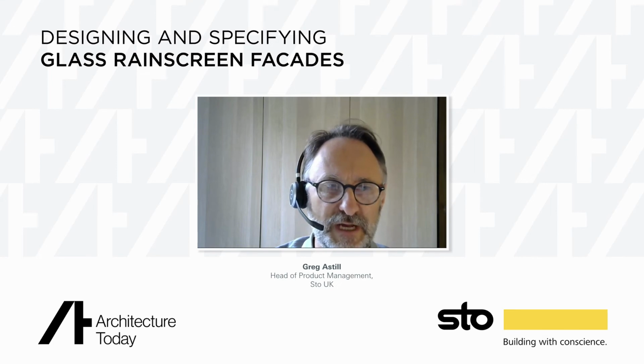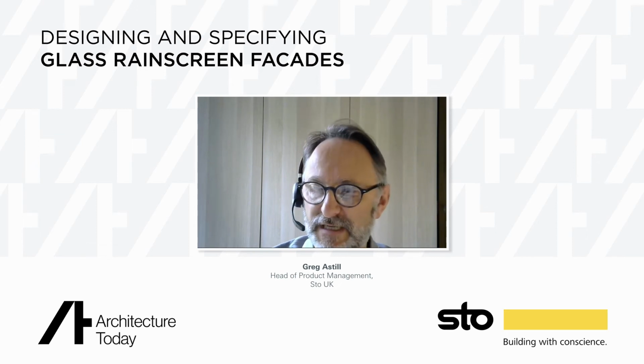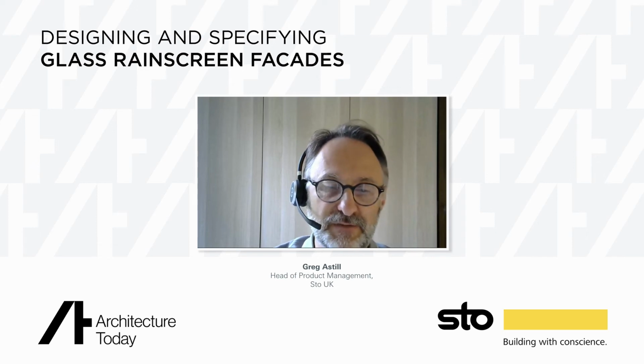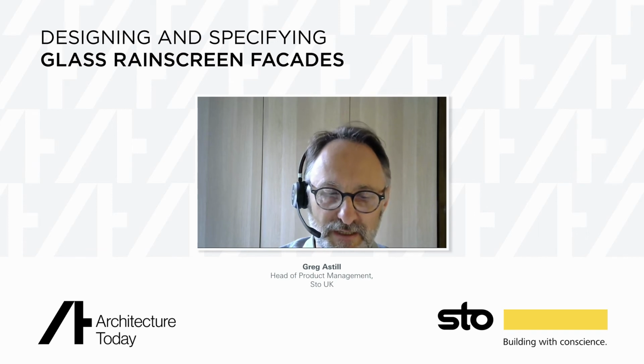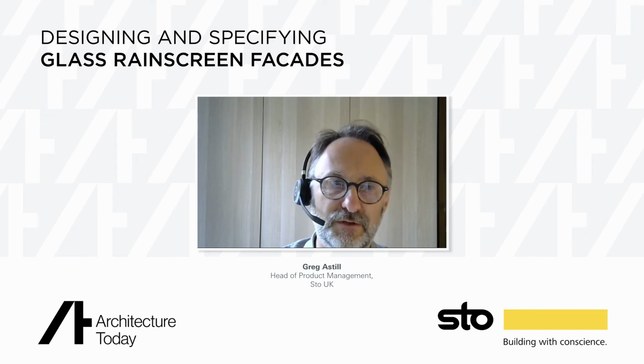So that intumescent material expands, blocks off the cavity, if you like, so the fire cannot get past it. It also stops any smoke going up through the cavity as well. So that's how they perform. But as I said, the cavity barrier design is usually part of the overall fire strategy for the building, so it incorporates all sorts of other elements as well, sprinklers and all sorts of other stuff. That's a holistic design, which is carried out by the architect, usually in combination with some sort of specialist engineer that would look at that.